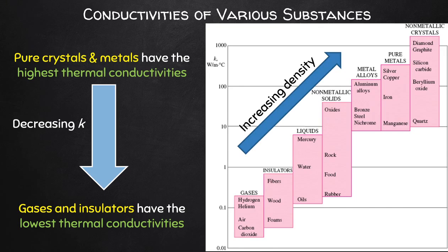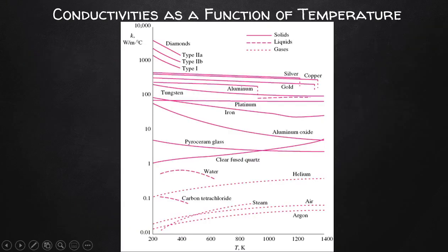And obviously I mentioned temperature. Temperature can affect thermal conductivity significantly if the temperature range is considerable, right? If it is wide enough. So for example, look at the very small variance in thermal conductivity for gold, silver, and copper between a temperature range of 200 Kelvin and 300 Kelvin.